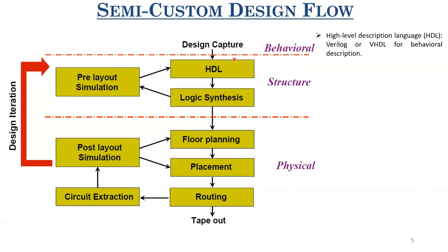Now that HDL code is given to a logic synthesis tool. This logic synthesis tool converts it into a gate netlist. That is, it tells you what the different gates are that will implement this logic, the relationship between input and output which you defined at the behavioral level, and how exactly those gates are interconnected. The most common approach is to make these gates as standard cells. I will explain what exactly a standard cell is in later lectures, but standard cells are basically laid out having the same height when you make their layouts. So I will discuss that later.